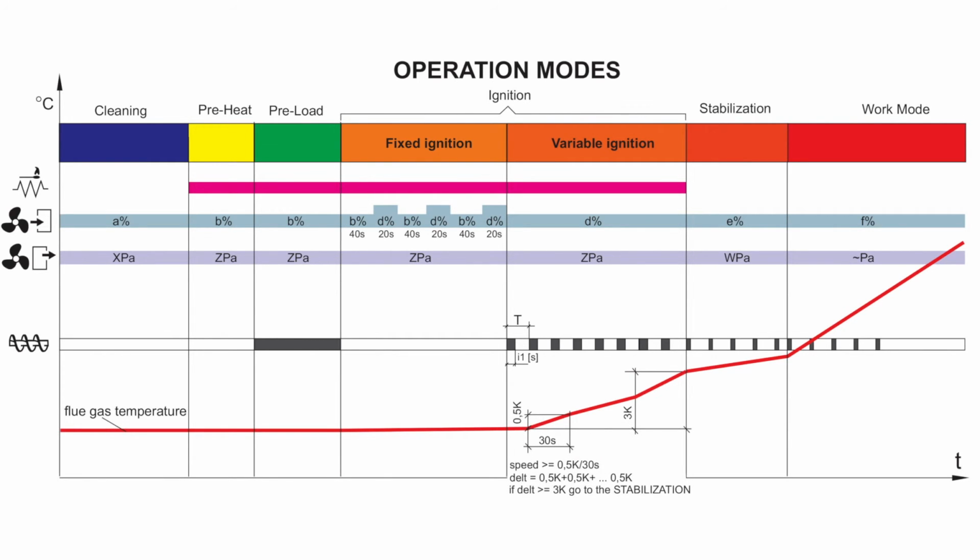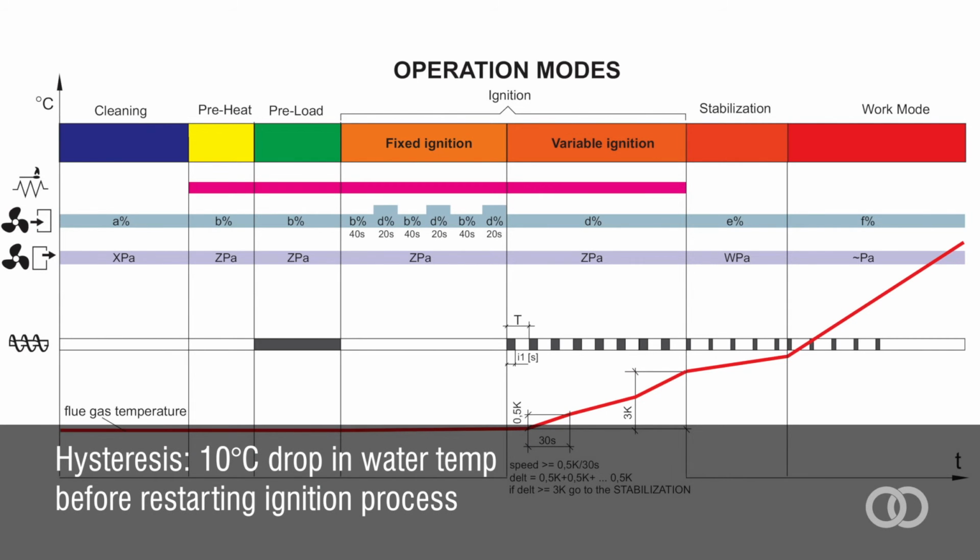The boiler operates on PID modulation, so will modulate freely between 30% and 100% of boiler output. Once it reaches the target temperature, it will continue to run at its lowest power for an extra 5 degrees Celsius temperature rise before going to the burning off extinguishing stage. Burning off lasts for a minimum of 7 minutes. Once burning off is finished, it enters final cleaning, which is compressor charging for 120 seconds and release of solenoid for 0.4 seconds.